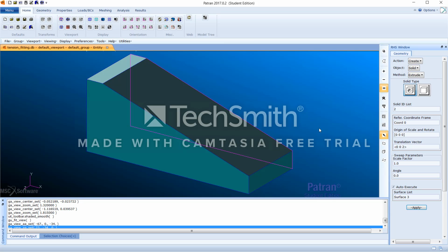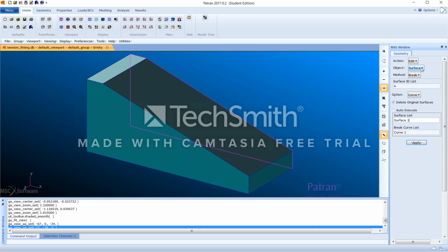Now we are going to edit a solid using the shell method. Select action as edit, object as solid, and method as shell. Enter 0.25 for thickness and turn off auto execute, and select the three faces of the solid and apply it.